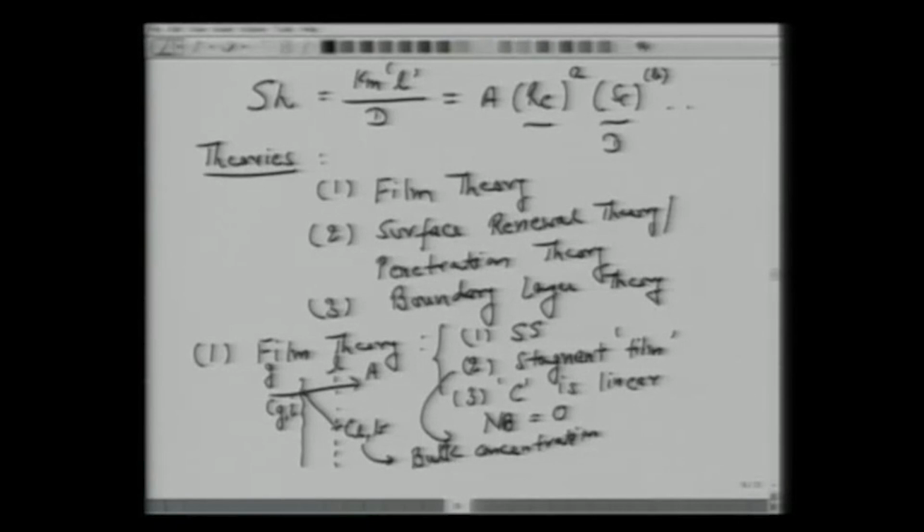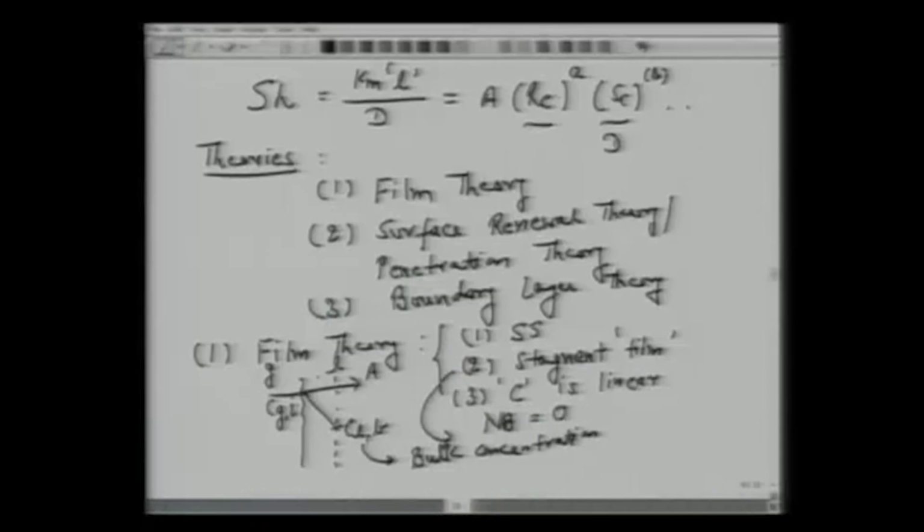All right. So what this theory says, let's see physically, is that if you have an interface of gas and liquid and some species diffuses, say sulfur dioxide from air into water, then we have a hypothetical film. This film is stagnant. There can be a flow parallel to this direction, that's possible, but in the direction of this diffusion flux of A, there is no bulk transport. So stagnant film means no bulk transport. So the first main postulate here is that there is a steady state.